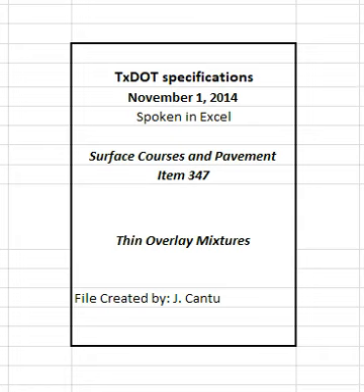The engineer may also obtain independent samples. If obtaining an independent asphalt binder sample, the engineer will split a sample of the asphalt binder with the contractor. The engineer will test at least one asphalt binder sample per project to verify compliance with Item 300, asphalts, oils, and emulsions.